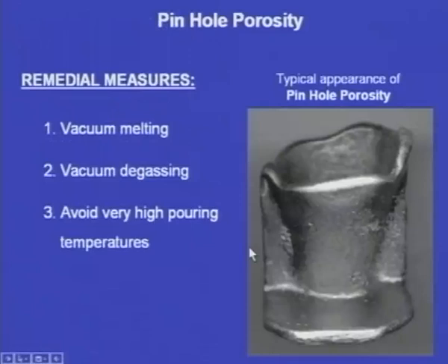Now what happens is, during solidification the solubility of hydrogen drastically comes down, and once the solidification is over, the excess hydrogen will be liberated out, and this liberated hydrogen will be coming to the outer part of the casting and forming pinhole porosity.